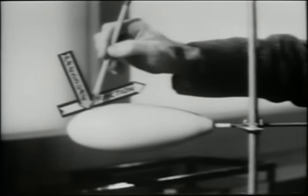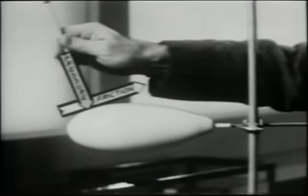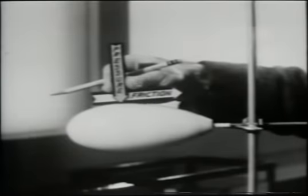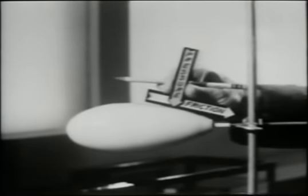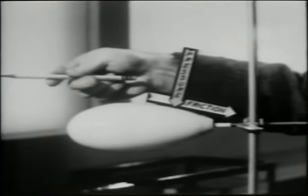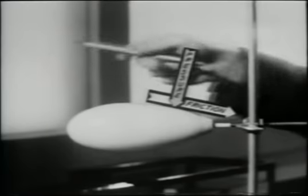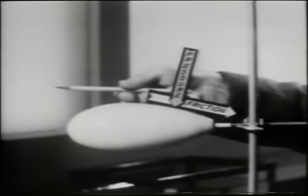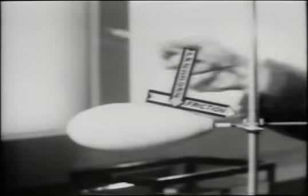At this point near the nose, the pressure force normal to the surface incorporates a positive drag component. At the shoulder, the pressure force has zero drag component, while here near the tail, the pressure force has negative drag components. That is, the horizontal component of the pressure force actually thrusts the object against the flow.